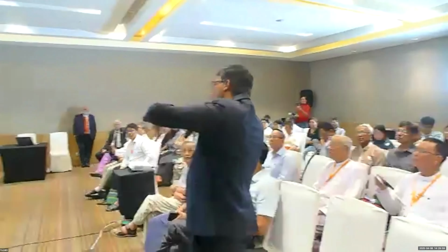I think I want to clarify what he's trying to ask. He's talking about the band in the wall, I think. The lintel. After the Gorkha earthquake in Nepal in 2015, before that we just used the wall. There was no provision in the code, I think. The wall could be constructed at any height. Now we have a provision that you must have a band, at least if there is no opening, then you should have a band at least at 4 feet.